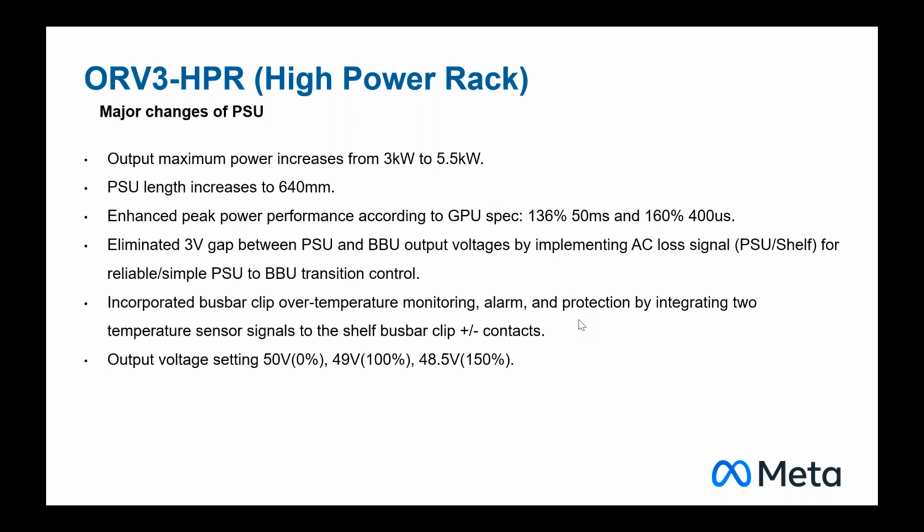And plus, the major power consumption is the GPU system, and David Moore knows better. The GPU system, they don't care, they take the 48 volt directly from the bus bar. So only a small portion of the system power, to my understanding, you can correct me, needs to be regulated to support things like 12 volt memories and fans, which need tight regulation. For those things, they can use a regulated DC-DC converter. There's not much difference in terms of efficiency and cost.